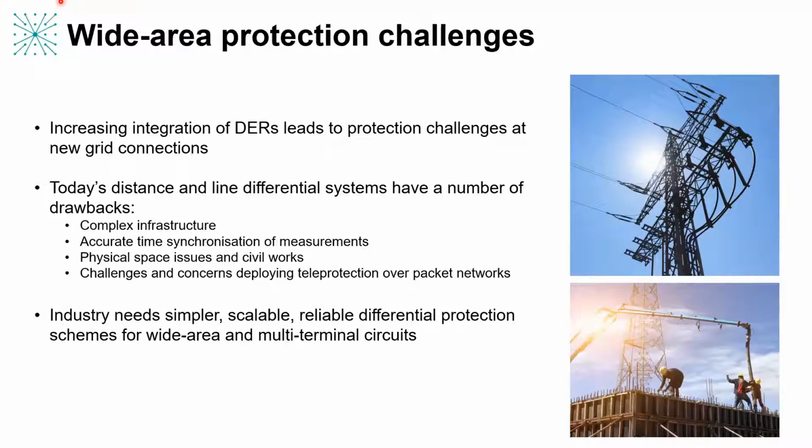Approaches to this will vary around the world, but it's not uncommon, at least in the US and the UK in particular, for this to result in circuits with 3 or more ends to that circuit, which lend themselves to particular challenges around electrical protection. Even in other territories where this is not necessarily the way these connections are made, any complex multi-zone circuit can be addressed in a similar way by this technology.